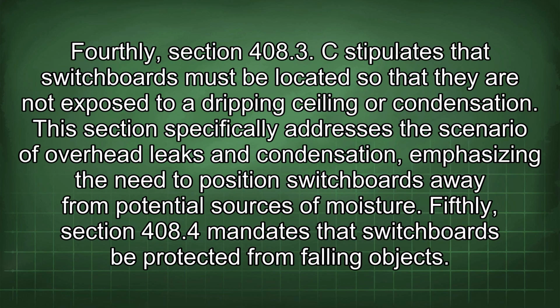Fourthly, Section 408.3 C stipulates that switchboards must be located so that they are not exposed to a dripping ceiling or condensation. This section specifically addresses the scenario of overhead leaks and condensation, emphasizing the need to position switchboards away from potential sources of moisture.